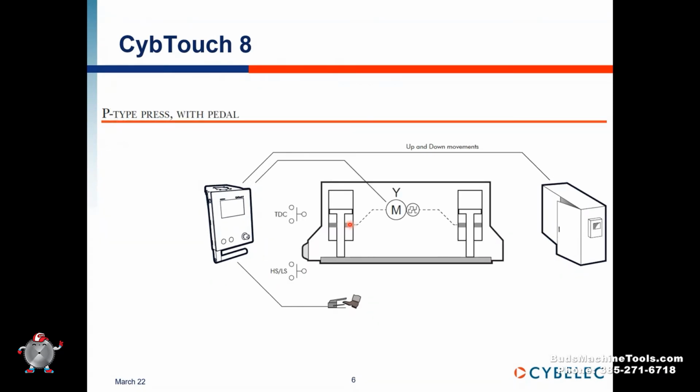Now, it's as shown a bit before. We move first this mechanical stop at the correct position, and then we open the valve and put the pressure here, so it goes down on the mechanical stop. To know where the beam is, we have switches.